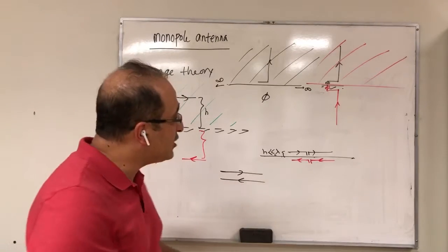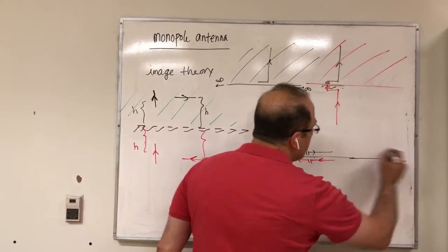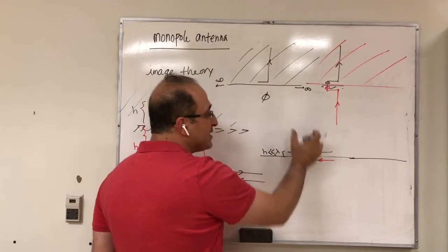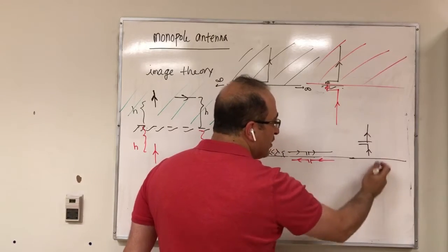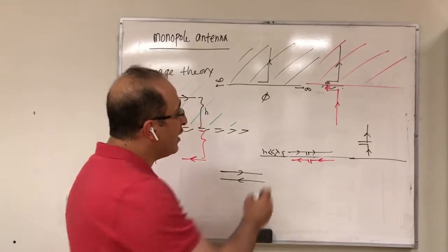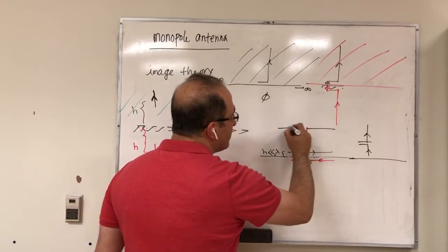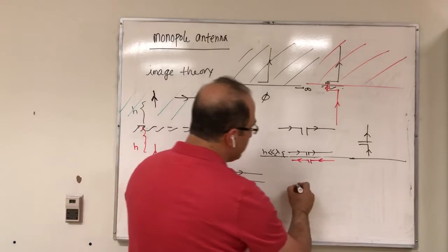So this is what's very important here: you shouldn't put a dipole antenna horizontal to a PEC, otherwise you get no radiation. If you want to operate a dipole close to a PEC, perhaps you need to either increase the distance or have it vertical like that, so image theory helps in this case, otherwise image theory cancels. If they are farther from each other like that, then the image would also be farther.